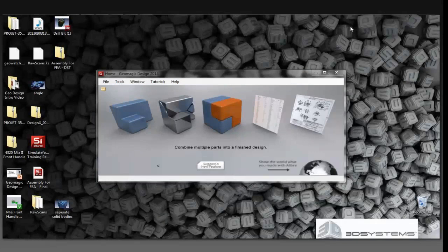So let's go ahead and get started. Today we'll be modeling, like I said, a pulley that controls the motion of the build platform, and we'll bring that into an assembly and use top-down design to create a sheet metal bracket in it. And then finally we'll document that in 2 dimensions, perform motion analysis on it and FEA on the assembly, watch it run, and then we'll bring it into KeyShot and apply some photorealistic rendering to it.